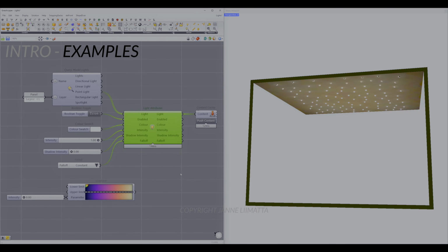By looking at the model, the first thing you notice is that you cannot even see the walls of the room. This is because we have 100 lights and the falloff function is set to constant. This basically tells us how it's going to calculate the light intensity on the walls or other objects that the light touches. So how I have understood this is that the constant function will apply the same intensity of light on all of the object surface. So for example, if the intensity of this point is 1, it's going to apply the intensity of 1 to here also, which is not how the light works in real life.